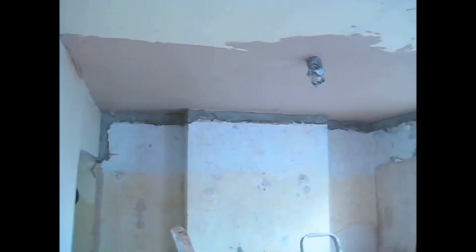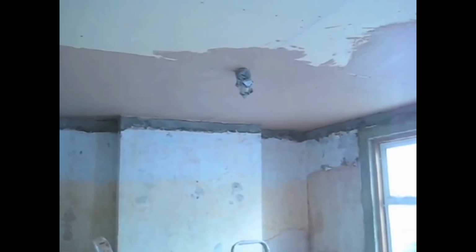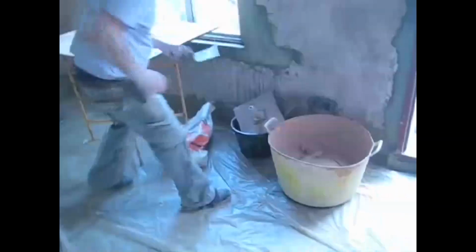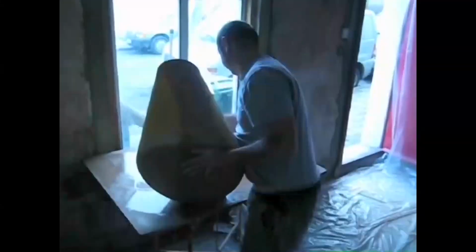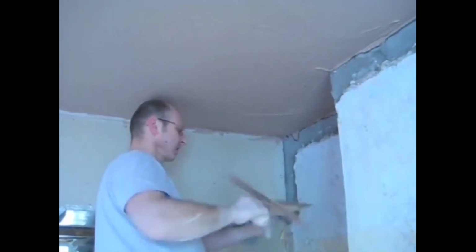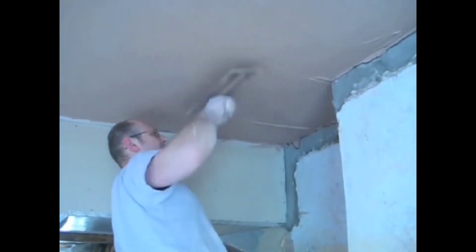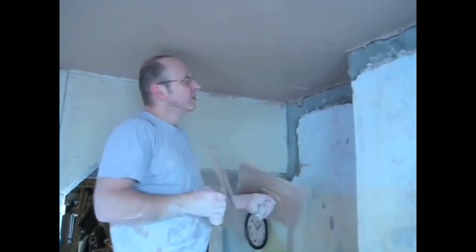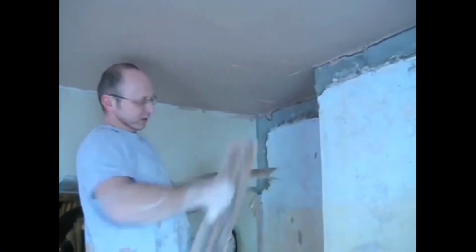Okay, so we've used 1 bag of plaster, and we've done the. Would you call that the base coat, Tim, or the first coat? Yeah, base coat. The base coat covered half the ceiling. Meanwhile, Tim has mixed up another bag of plaster. They put it all up and then just go whoosh, and there it was, perfect. Because all the volume of this one is going to kind of smoothen it out a bit. So it's really helped it. But it's got more work to do.